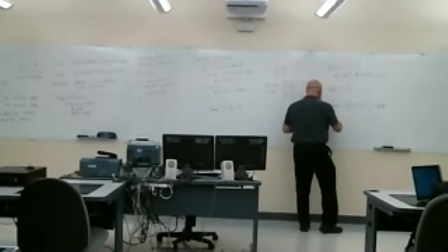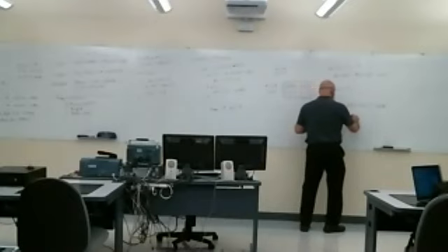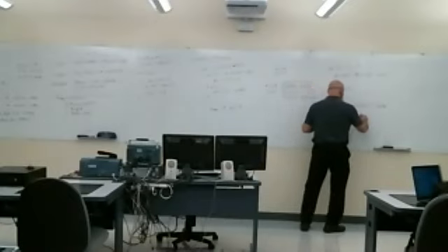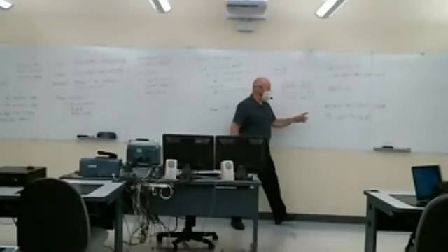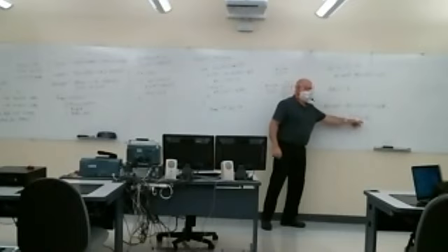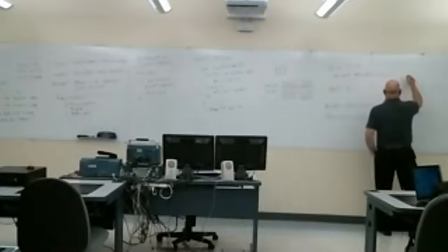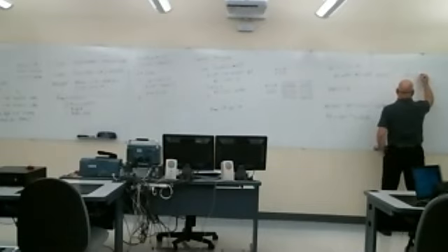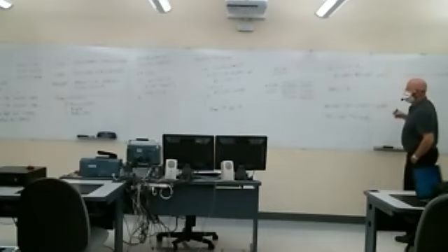Now, actually, in this code, he writes this in a shorthand syntax. This represents P4OUT is equal to P4OUT exclusive OR with that. Similarly, you could write the other one as P4OUT |= 0x40.